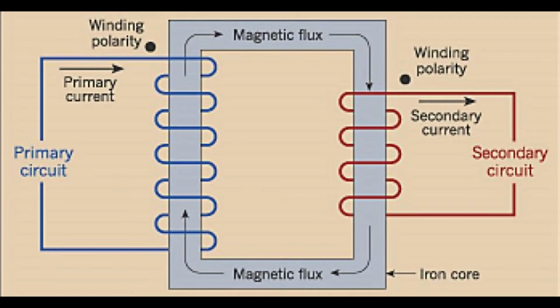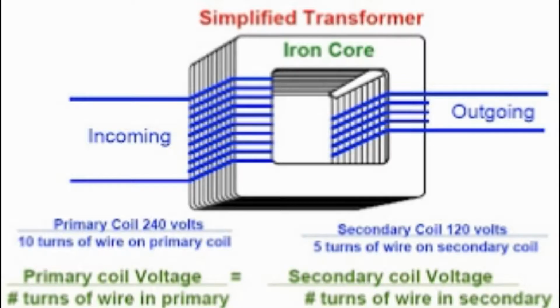Core. The transformer core is used to provide a controlled path for the magnetic flux generated in the transformer. The core is generally not a solid bar of steel, rather a construction of many thin laminated steel sheets or layers. This construction is used to help eliminate and reduce heating. Transformers generally have one of two types of cores, core type and shell type.